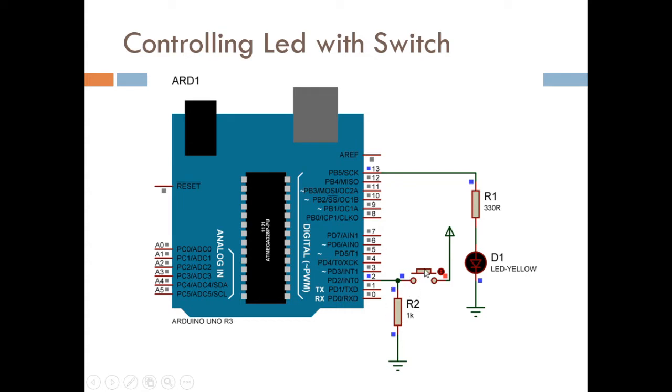So you may ask that when you are pressing this push button switch, whether the VCC or ground will be read from this pin. Since the VCC is going through this path, which is the least resistance path when compared to the other path where there is a high value resistance. So here the resistance will be more. In this path the resistance will be less. So when you are pressing the switch, VCC will be going through this pin, and when you are reading from the pin, you will be getting it as 1.